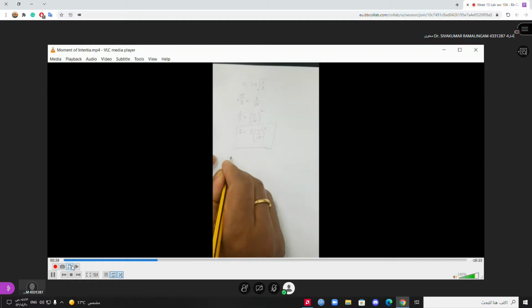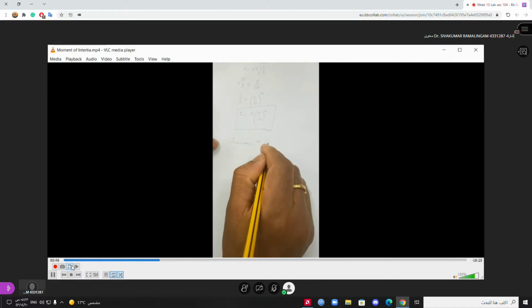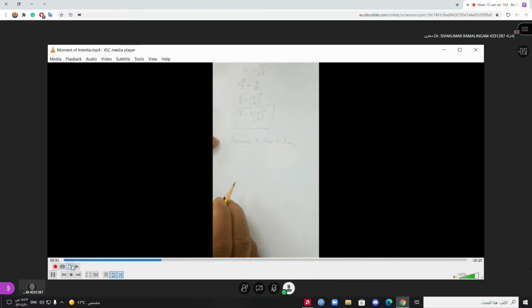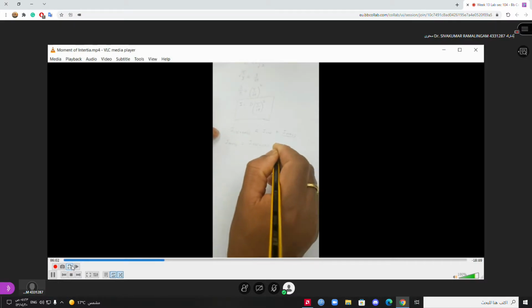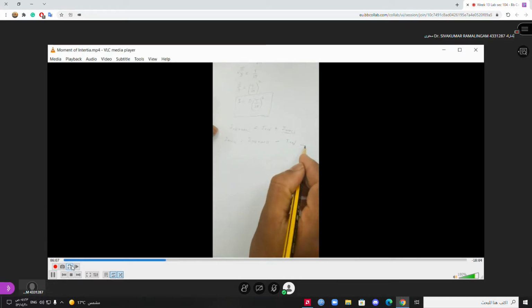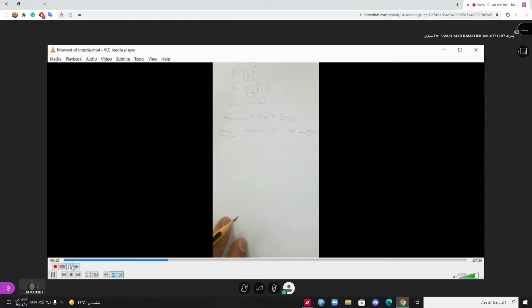Now let us see here. I rod plus mass, that means moment of inertia of rod and mass, I can write as moment of inertia of rod separately and moment of inertia of mass separately. I want only the moment of inertia of the mass. I mass is equal to I rod plus mass, which is together, minus I rod. The I rod we are getting in schedule number 1, and if you subtract this from this, you will get I mass.